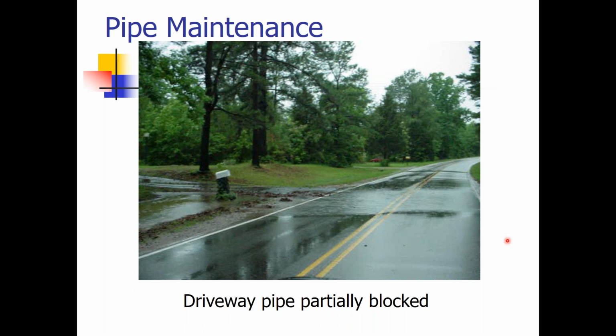We're inspecting them, we're doing preventative maintenance, and we're making sure that erosion is not causing our pipes to fail or any part of our drainage system to have a compliance issue or to not be able to move the levels of water that we have, depending on where you are and how much rain you have or the wetland areas. Oftentimes there's a lot of water being moved in a very short period of time. So just remember, as we're selecting our pipes and we're doing our ditches, we want to pick the ones that are going to move the water through as quickly as possible, but also drive those on a regular basis and just make sure those are being maintained. There's not debris, there's not overgrowth from vegetation. We don't have kids playing in things sometimes, which does tend to happen as well. So that would be my last comment on that.